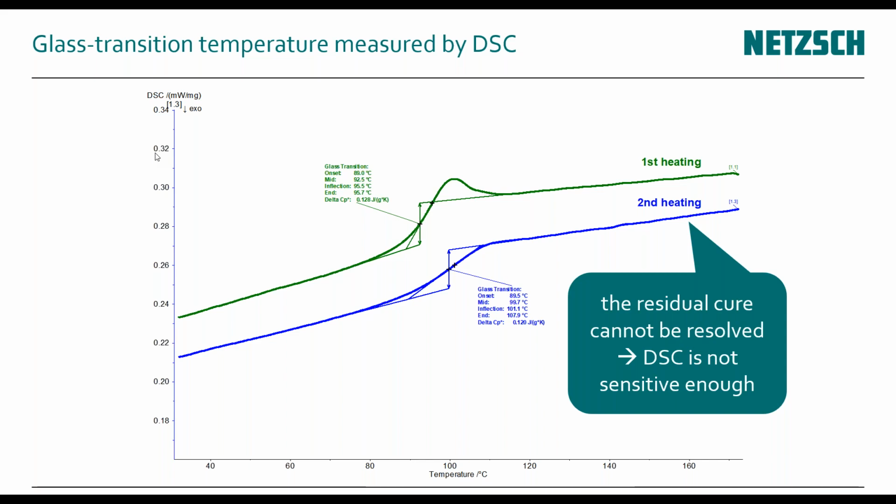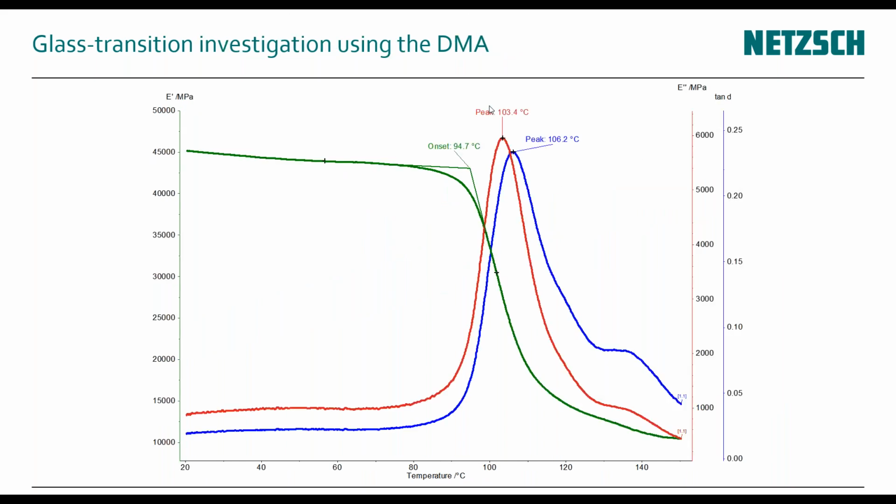Still, there are techniques. People are using temperature modulated DSC. You can look into this a little deeper, but for a very good reason in the industry, if we go to the next slide, DMA is the method of choice. I can just say that Airbus doesn't mess around with that if they need to know the degree of cure. And you see, we have a drop by a factor of 5, and that is much, much more significant than DSC.